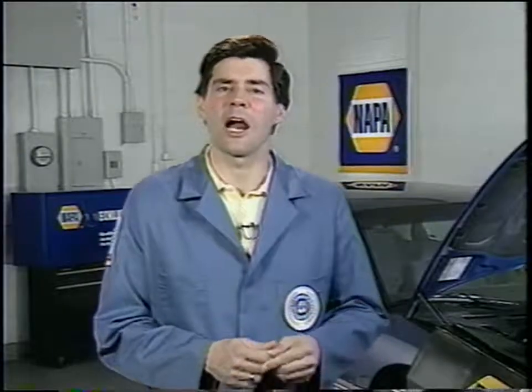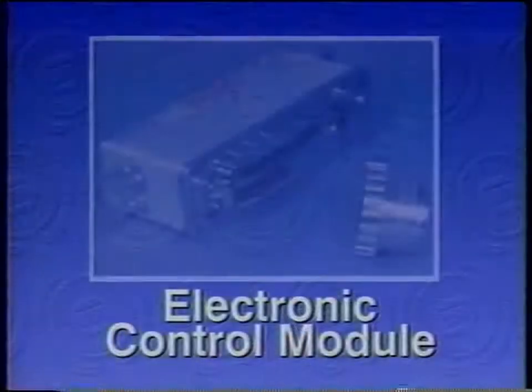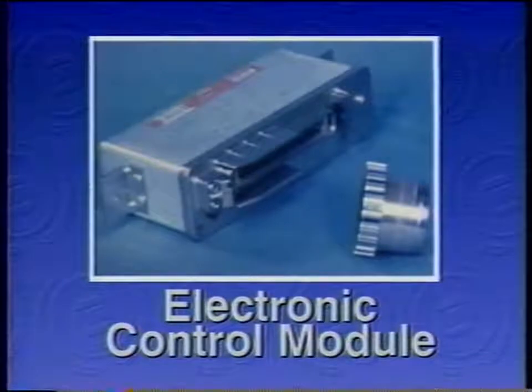Rear sensors are at each wheel, and front sensors are in the steering knuckles. The Bosch 2U electronic control module is more advanced than that on the Bosch 2. It's able to generate diagnostic fault codes, and eliminates the need for a dedicated ABS tester.